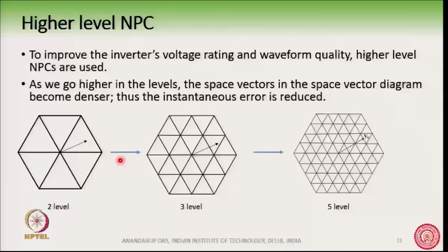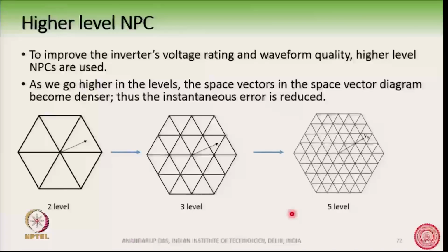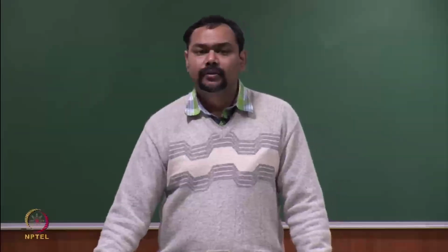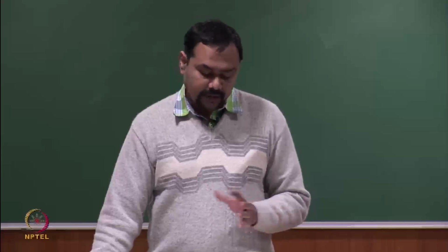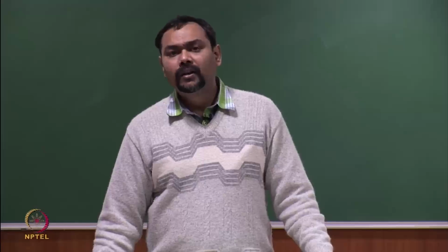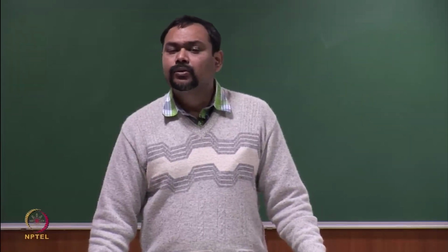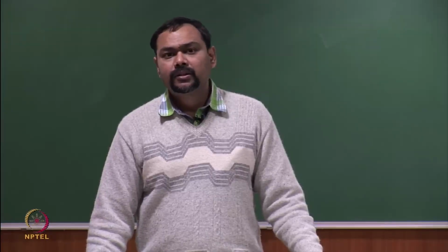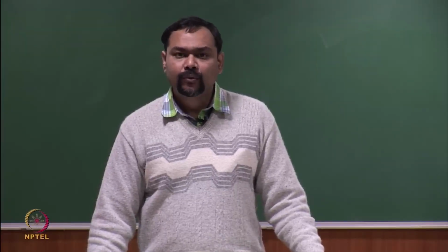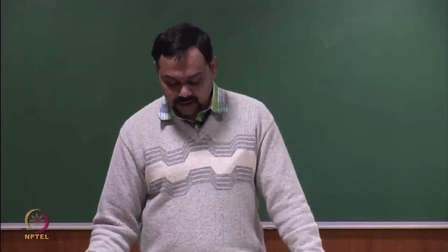We now see the possibility of having higher level NPC based converters. Often, it has been proposed in the research community that we can go from a 2 level to, in a conventional NPC, a 3 level NPC. Why do we not go for a higher level NPC? Now, why do we want to go for a higher level NPC? Because it will improve the waveform quality, and of course, it will improve the inverter's voltage rating or the converter's voltage rating.